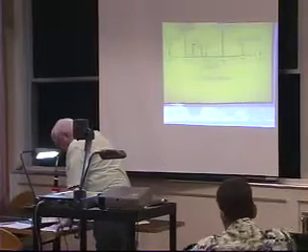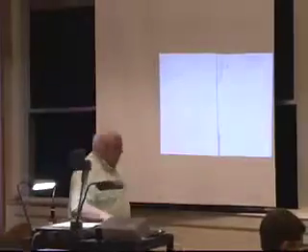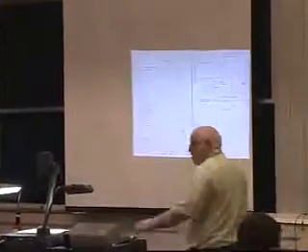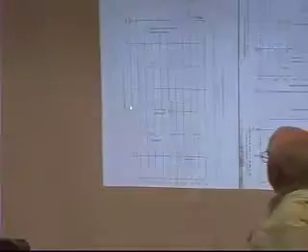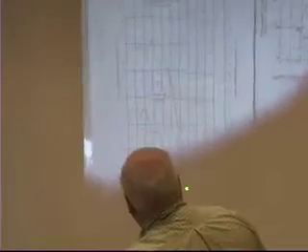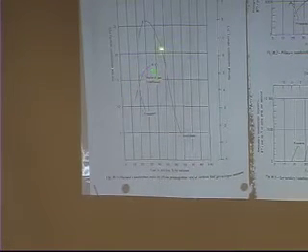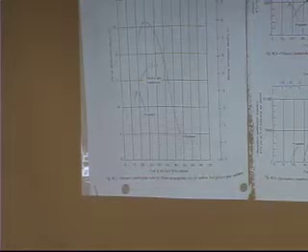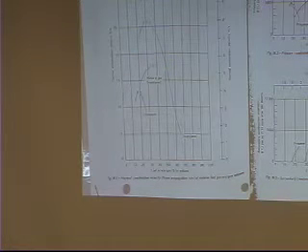Take it back with this. Okay, if I put this up, this comes actually out of the welding handbook for flames. This is normal combustion velocity versus fuel in mixture by volume percent. And I have acetylene, I have propane, and I have natural gas. And it has stoichiometric mixture, neutral mixture. Neutral mixture is where there is no excess oxygen, supposedly.